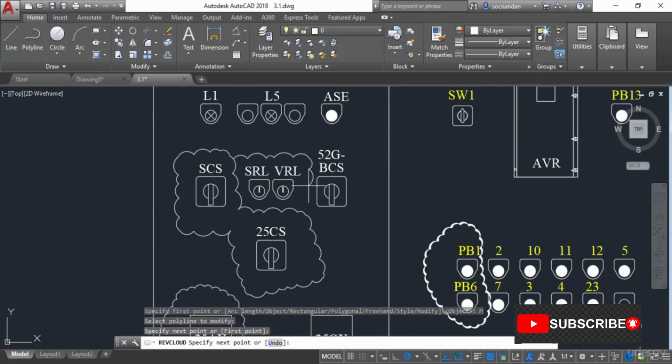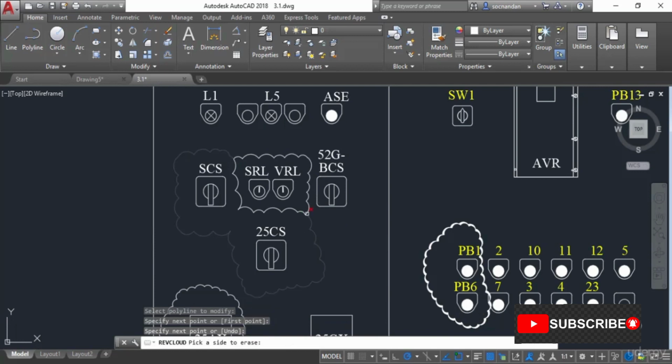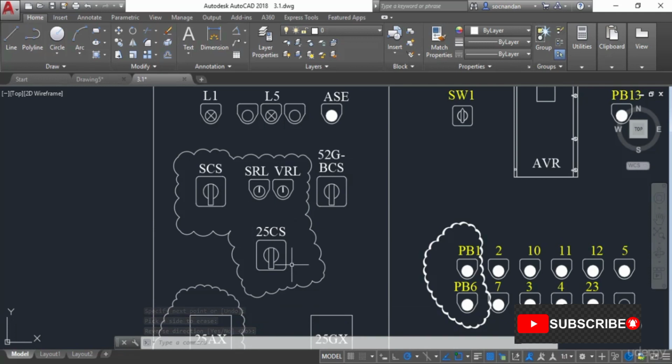So I'll click on this revision cloud, and now let's start making another one. So I'll click at this point, and then I'll click at this point. So now we have included both of these, but we also need to remove this part. So simply click on this part and the part will be removed. And now we have it perfectly in order, and we don't want any changes. So simply press enter, and here we have the final revision cloud. So in this way you can make many revision clouds, different kind of revision clouds in AutoCAD, and even you can modify them and change their type.